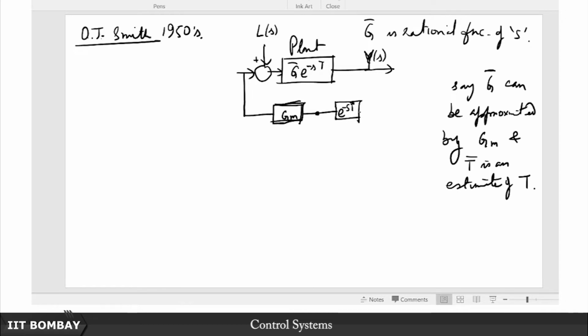And then what I do is, I have a summer here wherein I take the difference between the two. So remember, the common signal is coming into this. Of course, there is some load disturbance which I cannot measure, right? That is why I have not added this to my code here, because this is something that is coming extraneous to the system. I have no control over this. Okay. So therefore, the best I can do is whatever input is coming in through here into the actual plant, I am giving the same input to the plant model here, and I am comparing them. So I am taking the difference of the two.